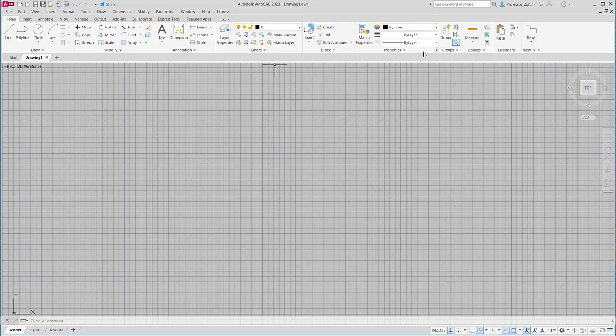The only other one I want to refer to right now is the Properties menu, which simply identifies the specifics of every line that we create. It identifies how we're drawing, in this case by layers, so the layer is active, that's how we draw. Thicknesses of lines, which we will leave for now. Line types, now line types refers to, and you can see there's only one here, continuous, different types of lines like hidden and center line and anything like that.